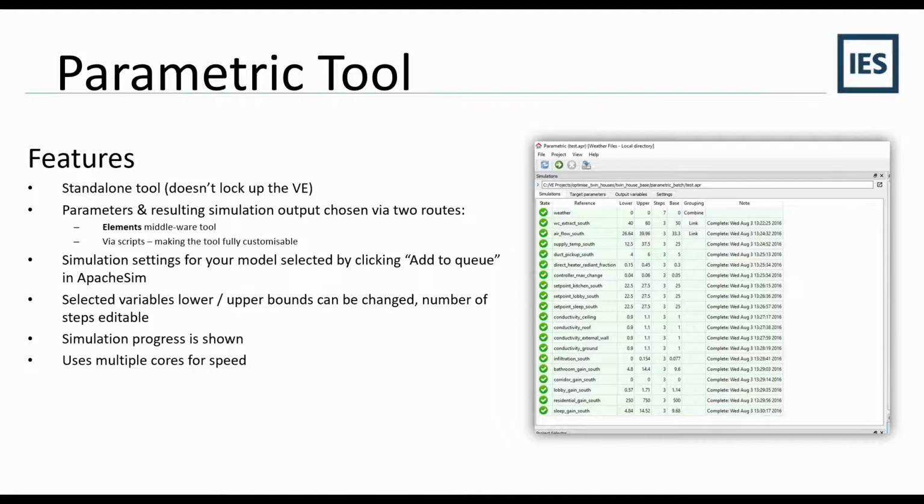Now, one of the key things here is that you're able to change variables within your simulations. So for example, what we're seeing there in the top line is that we've got a simulation running and there are going to be 7 weather files that are going to be used on that same simulation. So you'll set up that simulation, and you'll attach those 7 weather files. When that runs, it will then run those 7 simulations sequentially, or in parallel if you have multiple modules. And you're able to combine and link other simulations as well to provide an overall number of simulations, to create your group of simulations. I'll talk about that in the next slide in a second.